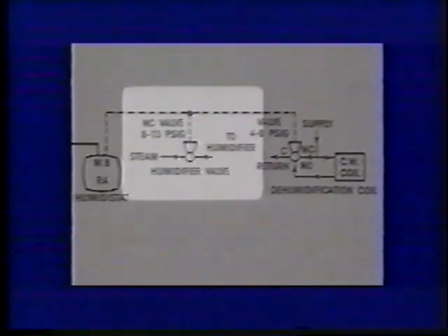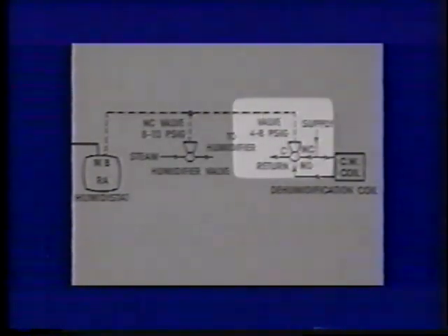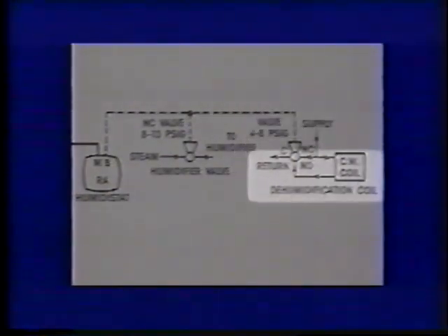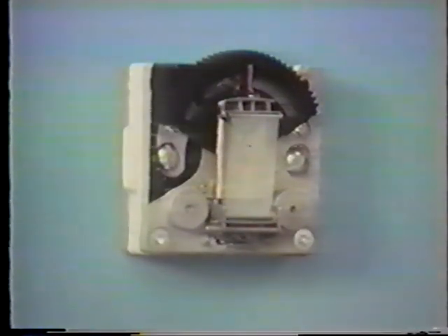As the humidity increases, the branch pressure starts to drop from 9 psig. When it falls to 8 psig, the three-way chilled water valve on the cooling coil opens, allowing water to flow through the normally open port of the valve and through the coil, which cools and dehumidifies the air being delivered to the space. This device uses a highly sensitive hygroscopic nylon ribbon as its sensing element. It is very important that you do not touch the hygroscopic nylon element because oils and acids on your skin will deteriorate the element and affect the accuracy of the device.